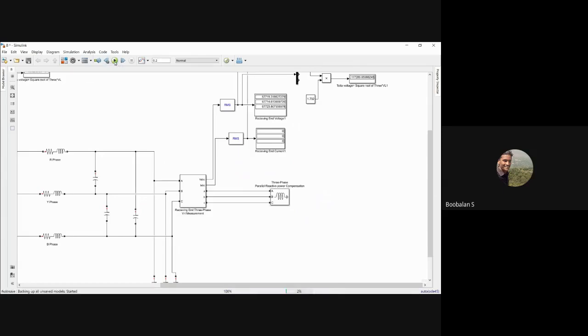Just one second, just run it one second. We are actually sending about 110 kV. Now due to this reactive power compensation, we actually removed about 7 kV. Now we'll have about the same voltage that we are receiving on the receiving side also. By adding reactive power compensation, you can remove the Ferranti effect, right? So these are the things we have seen in a previous class.